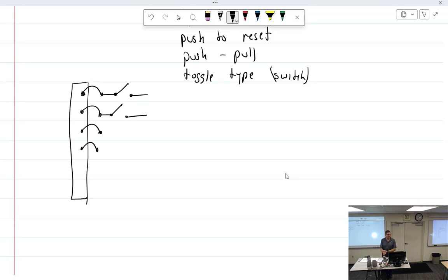Do you know how many times I've spent so much time looking for something? When we drop screws, nuts, bolts in aircraft, it's not an option to say, let's get another one. You have to find it, and sometimes it can take a long time. It's a 1 hour job and you just spent 30 minutes looking for a screw that you dropped. That's not a good time. Those little extendable magnets are nice. I've actually had to go get a replacement screw, drop it, and there, right there, is the other one.